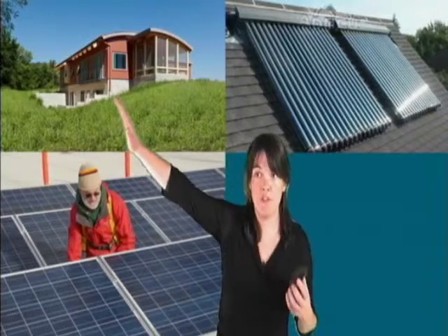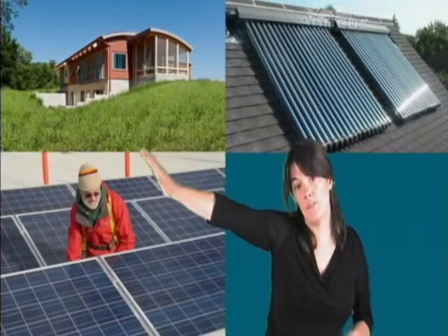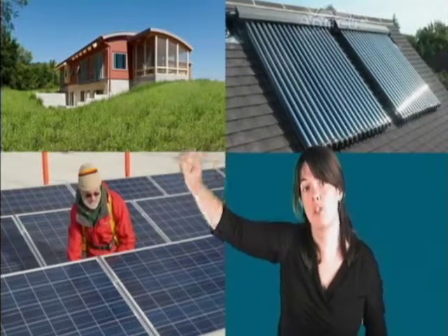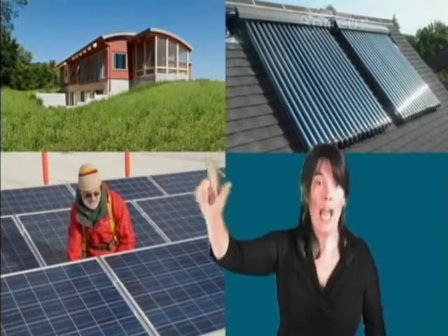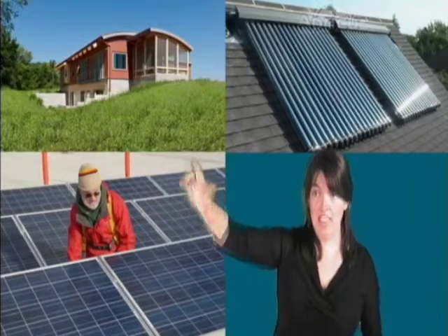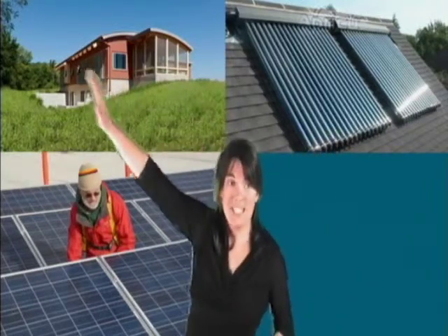So here's another example of passive solar, and this is a great picture of a passive solar house. Passive solar house means that you are using the sun's energy to help warm your house, or you're using shading to cool your house, but what you're doing is you're not using as much energy that comes from coal or any active source, natural gas, things of that matter. And so what we can see here is we'll see a few different things. You'll see windows that are predominantly on the south and or west side of the house that are going to be using that for both natural lighting and for heat.